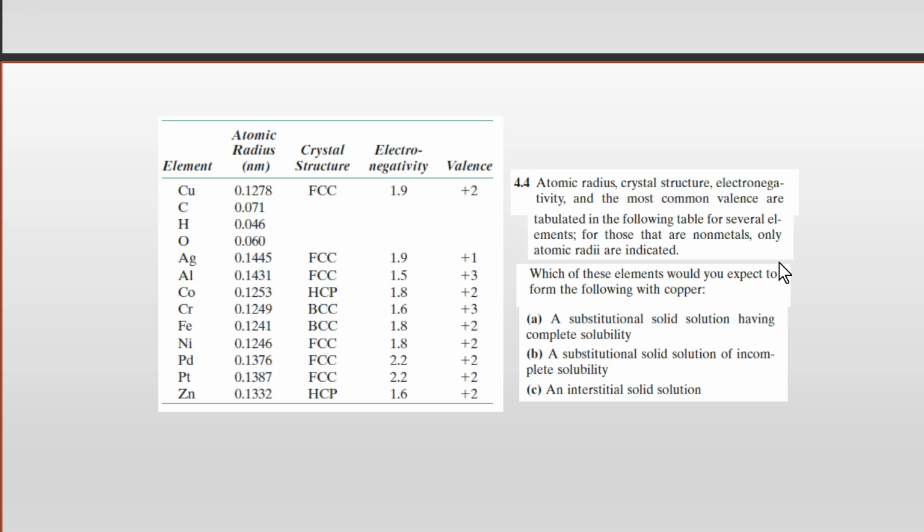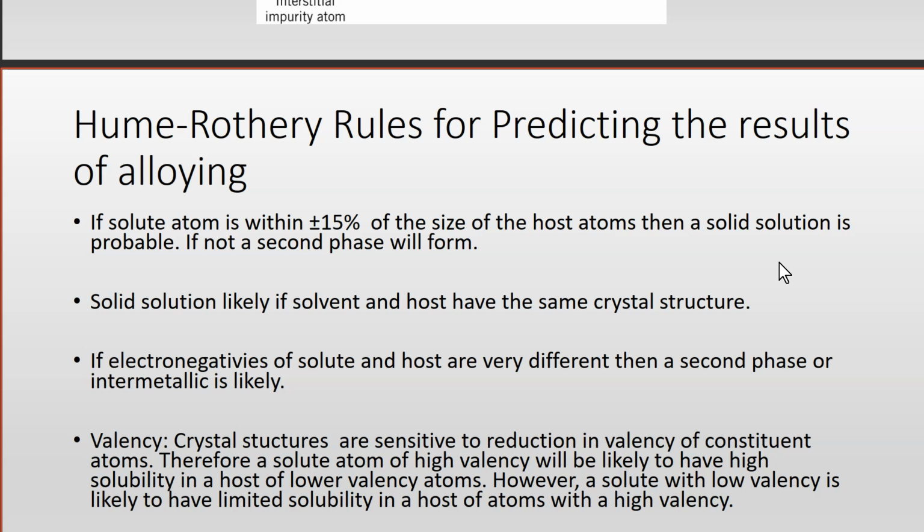A substitutional solid solution having complete solubility. Okay, so let's have a look. If we want complete solubility, then we want to meet all of these Hume-Rothery rules. So first, let's have a look at the atomic size.